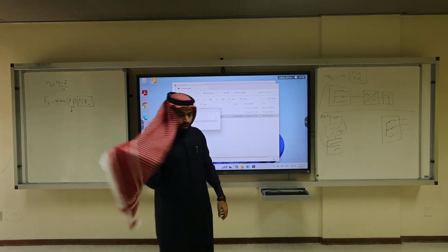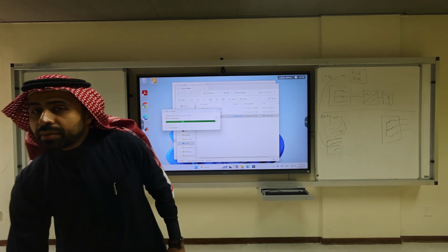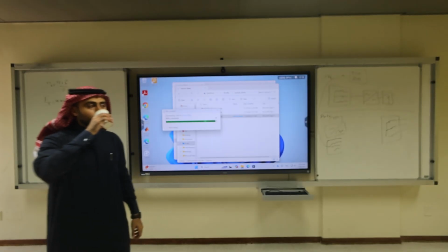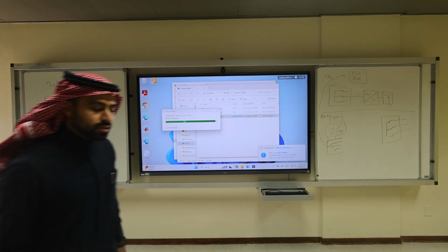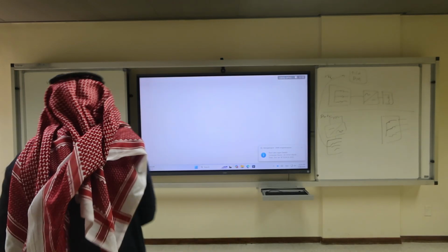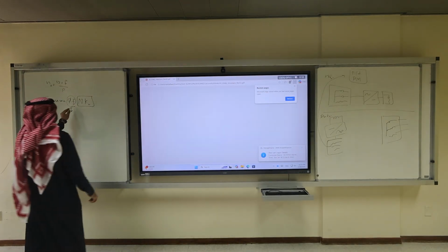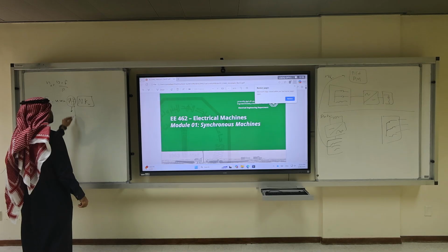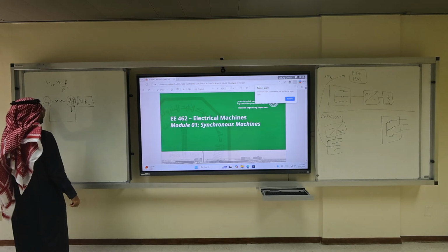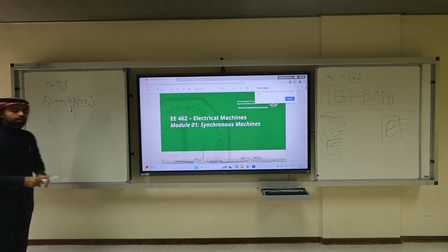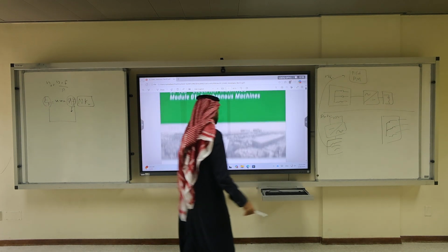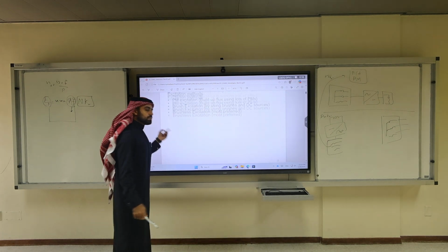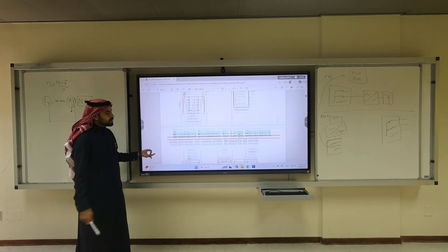Okay. So what else did we talk about? We talked about the importance of noticing the clear relationship between the frequency and the induced voltage. If you want to change the frequency of your generator, you have to change the mechanical speed that you're rotating at.